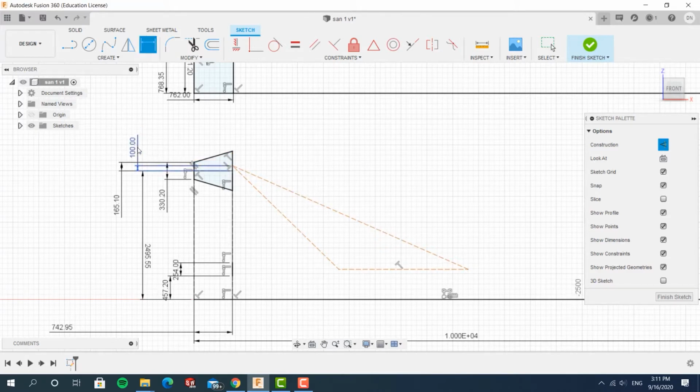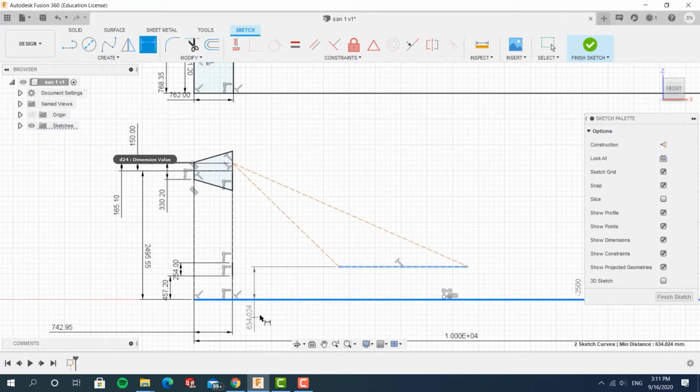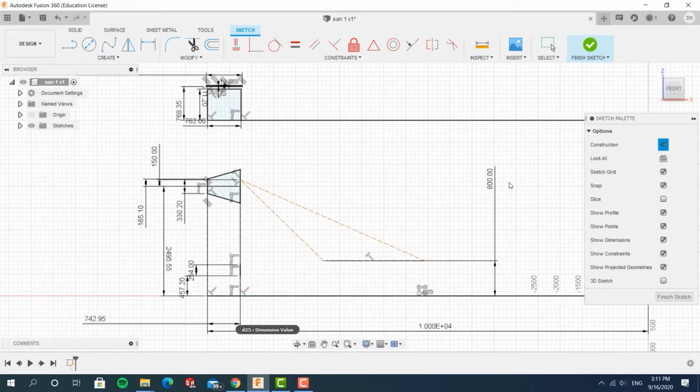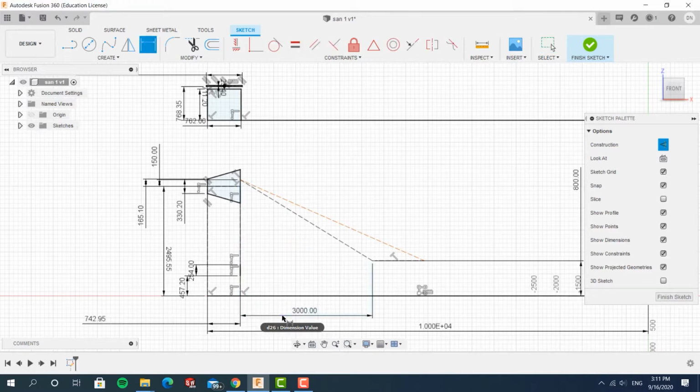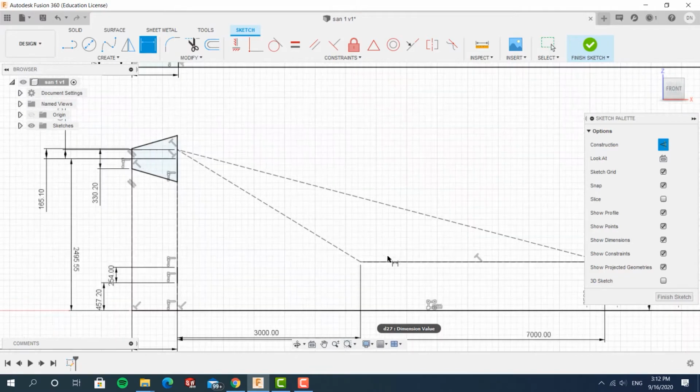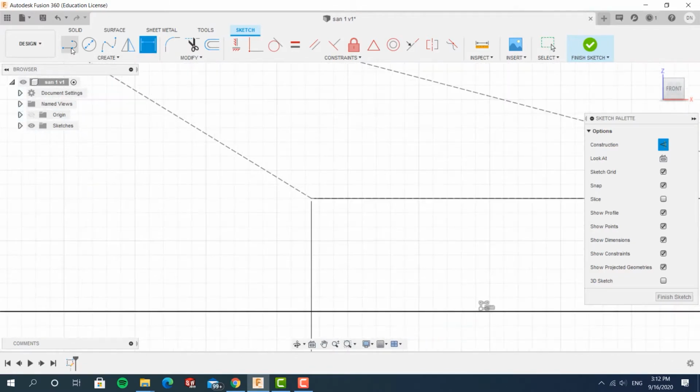For example, as we're drawing a shooter mechanism here, I'm drawing out the trajectory that I want, and basically by drawing that out, I'm drawing out the space between which my robot can actually score the goal. I'm representing the trajectory of the closest point and the furthest point with two lines, as you can see here. Because we're using a two-wheel shooter, I expect it to fly out pretty fast. That's why I'm just using a straight line to represent the trajectory.